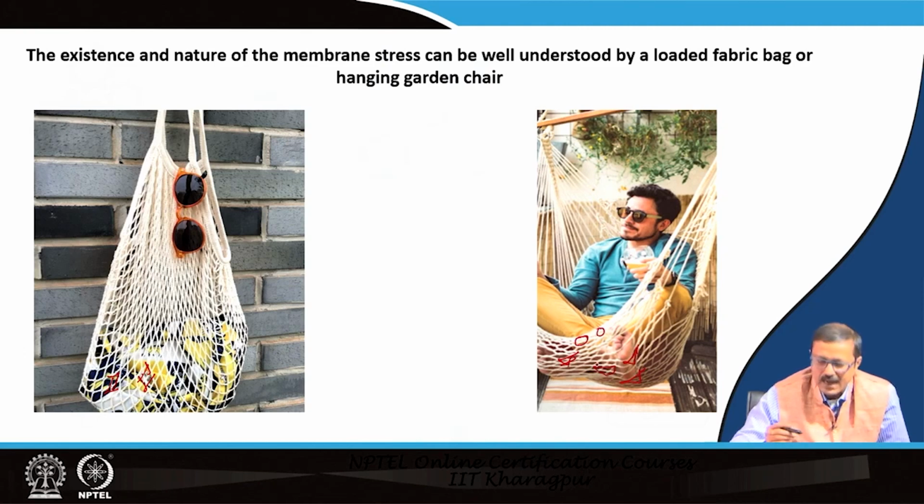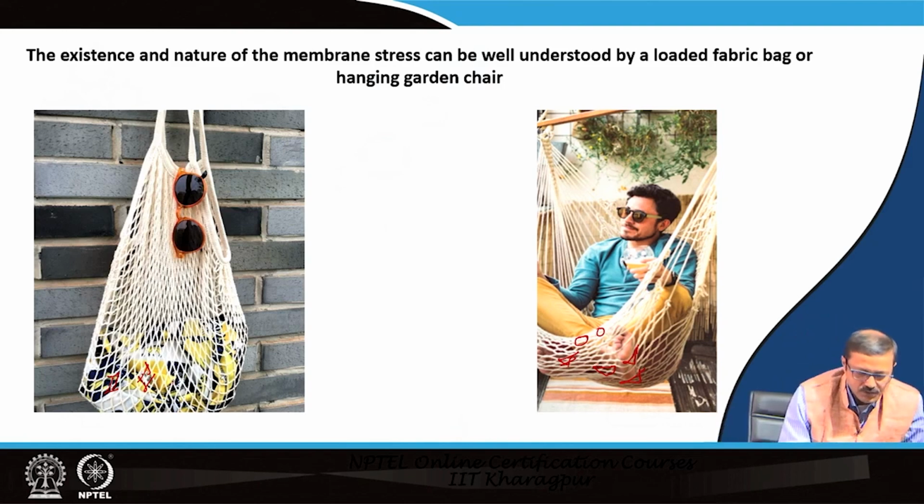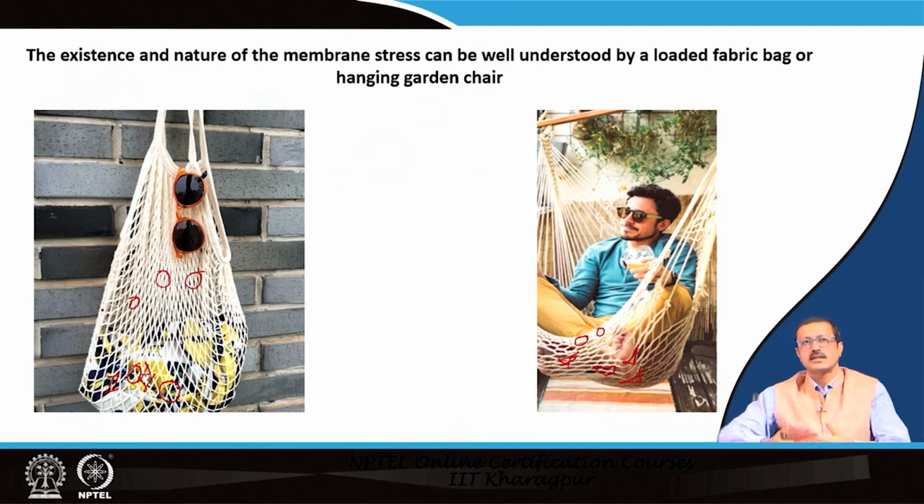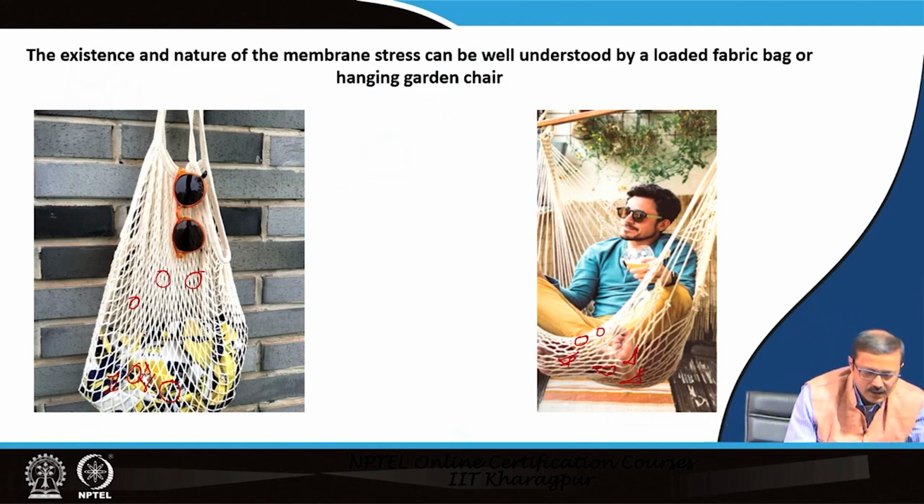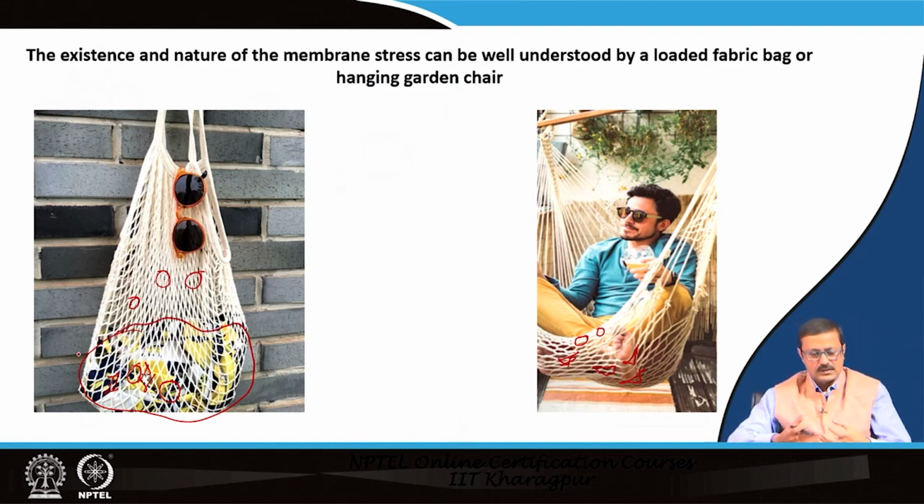Okay. So, that will beautifully show how this membrane stress is changing in its behavior by virtue of the elongation and contraction. Wherever there is elongation there is a tensile stress, and wherever there are compressive stresses, those are short and very densified. But you remember this is a case of an arch. I am sorry, this is a case of a cable, but the shell is an inverse of that cable. So, these portions are going to be mostly under tensile stress because they are elongated, stretched.